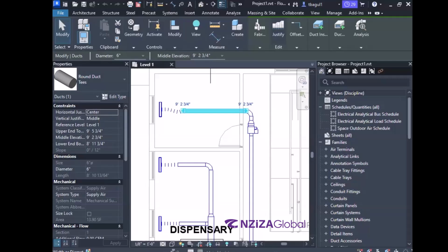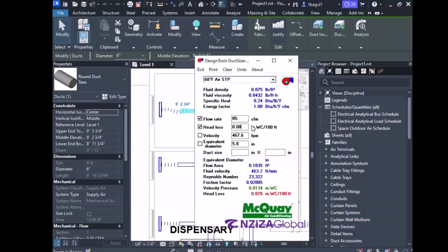I wanted to repeat the question. All right, so for the folks online, the question was: are there any parameters that affect the 0.08 inches per 100 foot of pressure drop that we are talking about? So yes, it does come into consideration. Sometimes the project will push our ducts to be a different type as compared to whatever GI we might have for a regular duct, right?